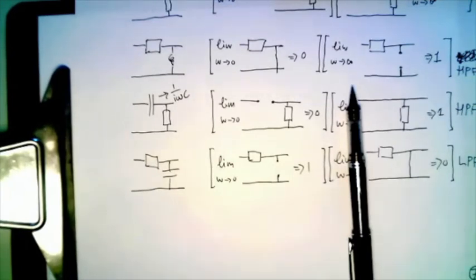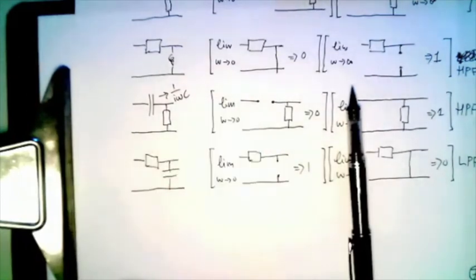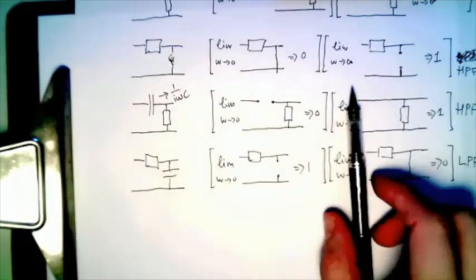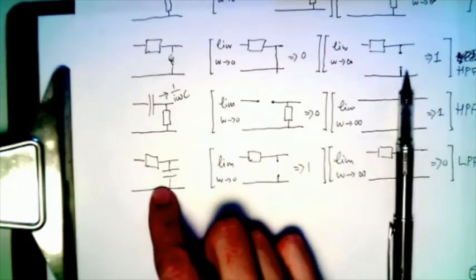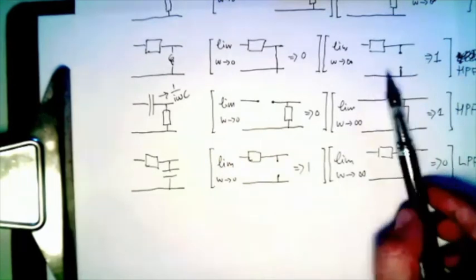For instance, if you have a transformer and you're trying to convert the AC signal that comes from the outlet to a low voltage DC signal, then you can flip it over, make sure that it's going in one direction, but then you still have some 60 Hertz ripple, and you usually get rid of that with a low pass filter, so it kind of smooths it out.